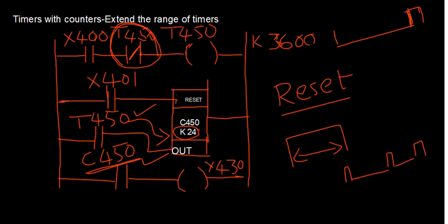Before that, because of the time limitation of your timer, you would have the delay of 1 hour each, which is going to activate your counter at the end, and that will make your output be activated. This is important for us, because every time upon the increment of the counter from 1, 2, 3 and so on, your timer should reset and start recalculating from the beginning till the 1 hour time delay is completed, that is 3600.